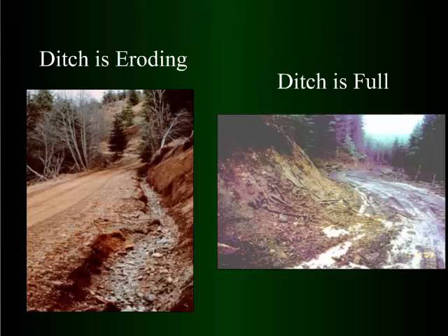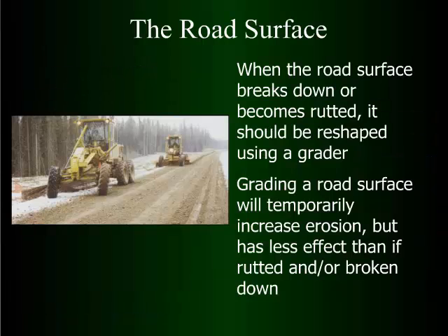We've seen this slide before once again, but as far as the maintenance goes, if this keeps cutting, you can see right here where the trucks are running to here is not very far. It wouldn't take too much for this to start eating away your running surface. So in this case, the ditch can compromise your running surface. When the surface of the road breaks down or becomes rutted, you want to reshape it. Ruts obviously accumulate water, and as fast as you can get it spread back out again before the next rain, it'll help keep the road from disintegrating too bad.